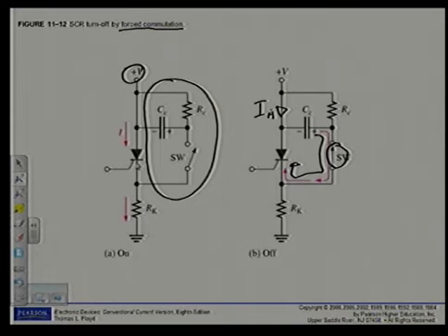So if you need to use an SCR or design a circuit using an SCR, you will go to a data sheet to determine what kind of SCR you will use. You will get information there, as mentioned here on page 560: the forward breakover voltage, holding currents, gate trigger current, average forward current, and so forth. Okay, so familiarize yourself with those terms, which you will also find on the data sheet.